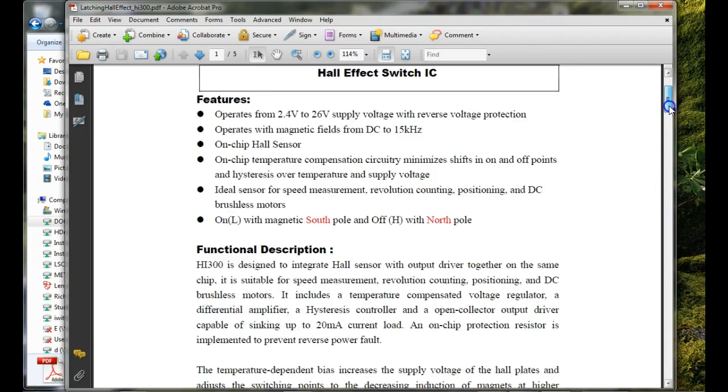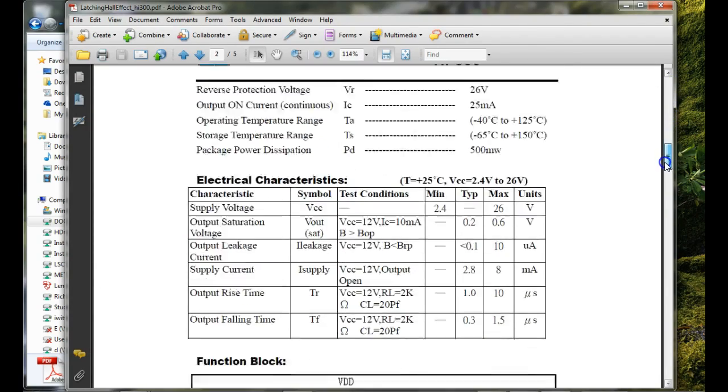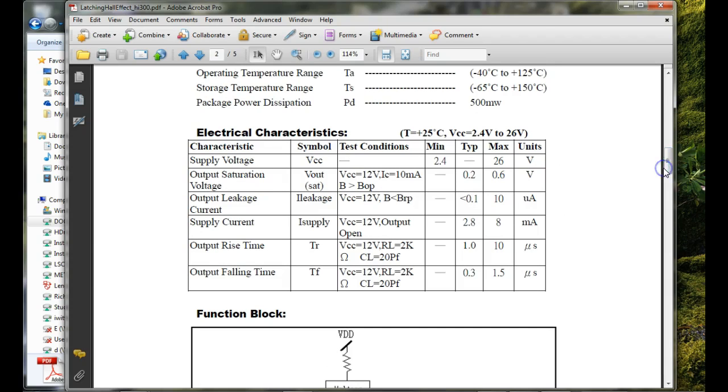And then what we look at is electrical characteristics. So this guy could be anywhere from a minimum of 4 volts to a maximum of 6 volts. So this guy's got a real wide operation range. But you can't power it on 5 volts and expect to get 24 volts out, right? You'll never, ever get what you powered up. In fact, if you put 5 volts on it, you're not going to get 5 volts out, because that would mean the thing would be 100% efficient, right? That makes sense. We're powering it up on 5 volts because of what I'm doing on the signal output.